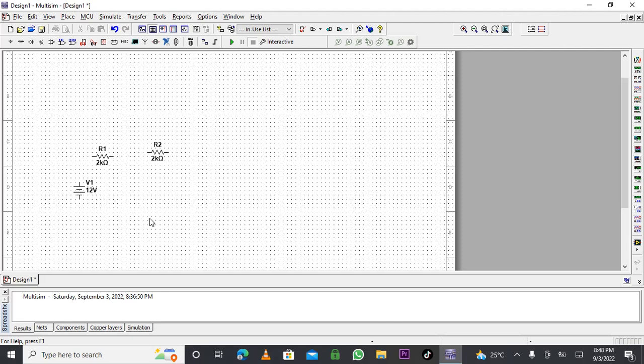So how can you connect? If you bring the cursor here, you see the cursor changes. That's when the cursor is connected to the line. And if you drag it, go there, just one click, just to make an anchor, and another click. So this is a connecting wire between the two elements. Do the same thing here, and one click, and that joins the two elements.